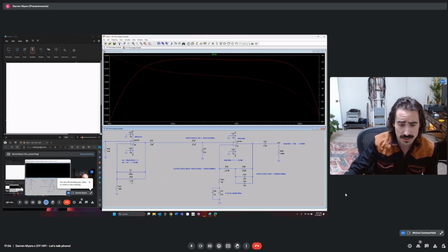Yeah, and if you look at the lower... Yeah, the lower value will dominate. It's going to extremely dominate the overall impedance. So we don't care what the individual values are here. We care about the paralleled value looking into this node.